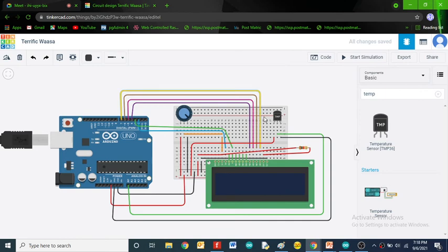You can see the LM35 is the input device, which is hooked to the A0 pin. We already know the LCD operation. Just read the information, convert it into the actual degree Celsius value and display it on the LCD display. This is my requirement.